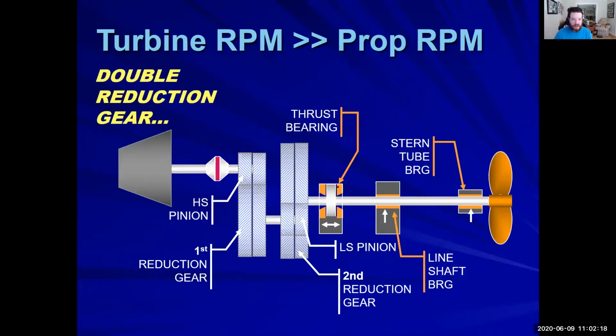Now, for anybody who's been down in the engine room, we have our thrust bearing. This thrust bearing is massive. The nuts on it are like this big. The bolts are massive as well. And that is our physical location. The thrust that is produced from that propeller goes into that thrust bearing, into those bolts. And that is the point where the ship is being pushed through the water. That is the singular point on the ship which takes all the thrust and moves that vessel.